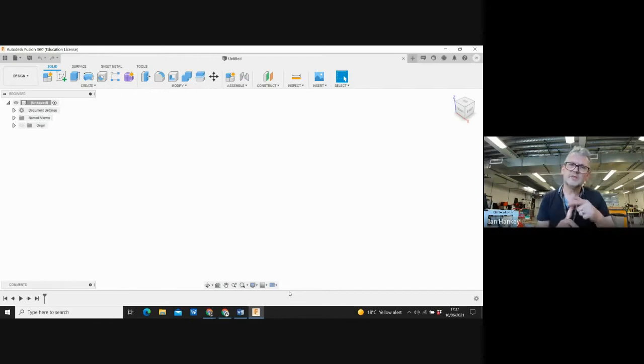So as long as we save it in a particular format, and that's generally STL, as Owen said last week, which stands for stereolithography. It's quite a big word. I don't even know what it means, but STL is a kind of 3D JPEG, which will open in anything. There's another very popular file format as well, called OBJ. So either STL or OBJ, whatever we save from Fusion, will go to any 3D printer.